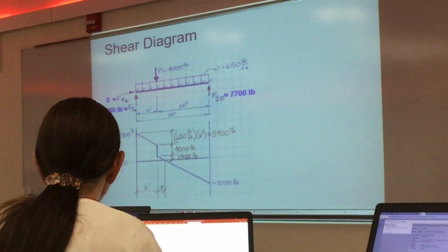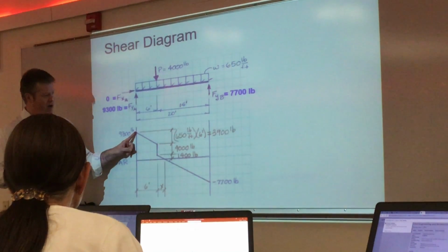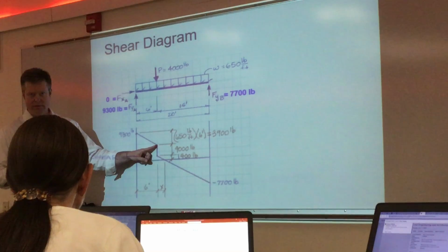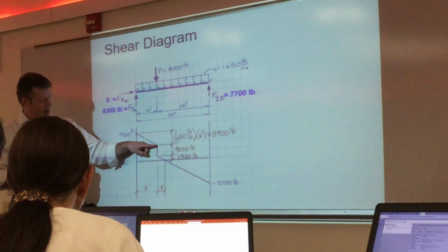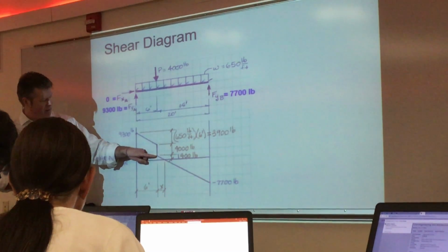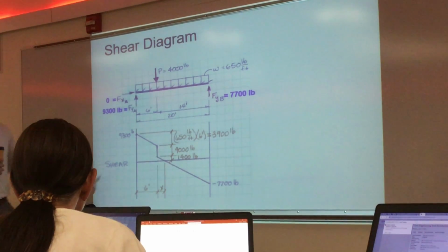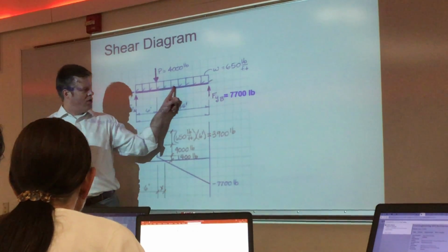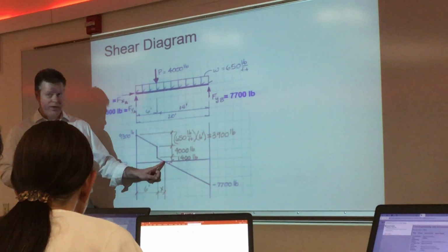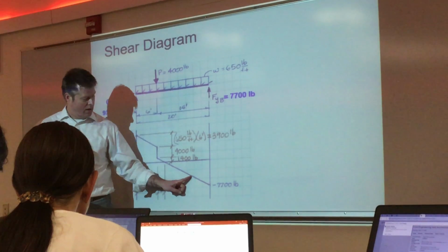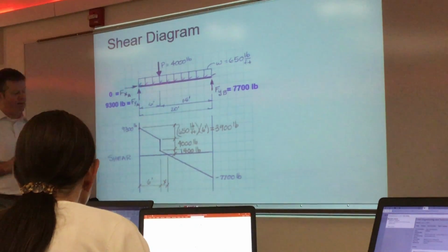It's an interval. So 9,300 minus 3,900 gets me to that. I don't have the math for that because they didn't give me that. They might give me that point if I keep clicking. Spikes down 4,000. Now it gets to 1,400. Then my uniform load starts again, and it goes all the way to the end of the beam. The uniform load keeps sloping down. Don't worry that it crosses 0, just let it keep going. All the way down to the point, and it should at the end equal 7,700.